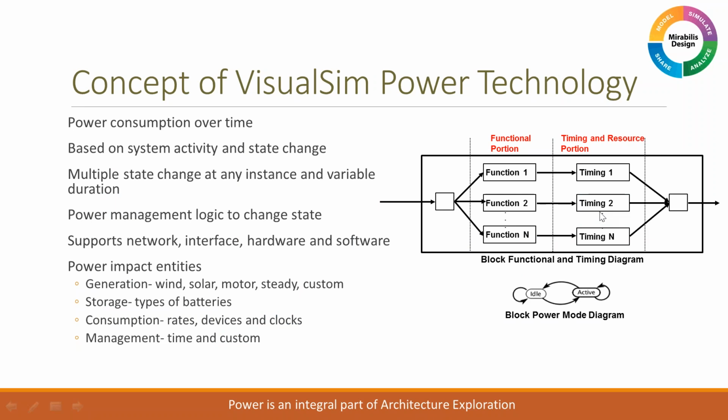Now, if you take the concept of power, one of the things most people do today is look at power as an afterthought, where I'm just saying, okay, I'm doing this function, so there's a delay. What VisualSim does is take it to the next level, which is to look at it as activity-based and state-based power analysis: at any instance of time, each device is in a different state or is moving into a change of state.